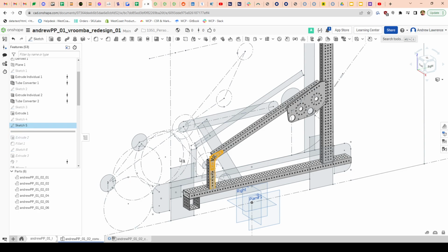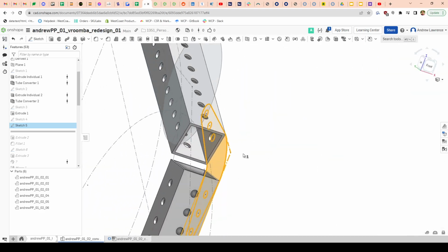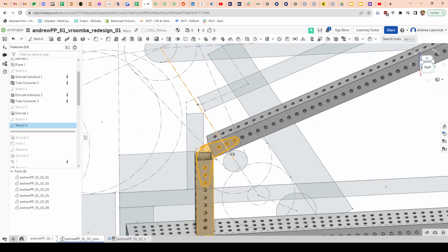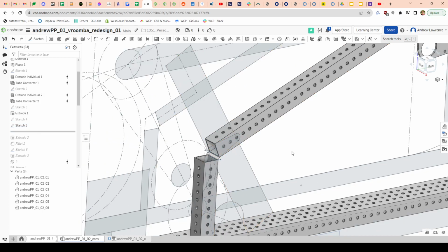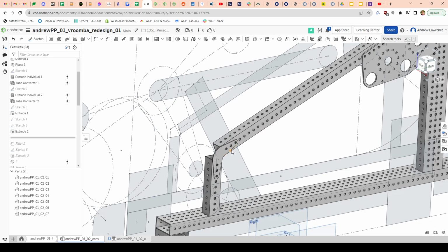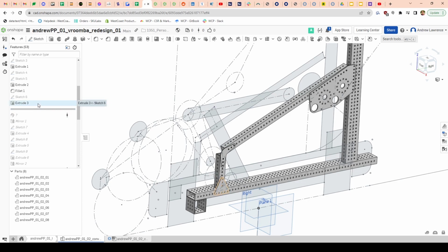Going on, after that, I made a gusset with a sketch. You can use the gusset generator feature script. I just want to do something specific that's made on that tube. And you're noticing how we're trying our best to model the parts as they will be in the assembly. Put it in the right spot. After that, let's see what loads. I get another gusset.